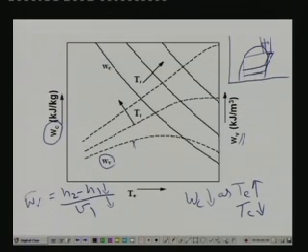So ultimately whether this reduces or not depends upon the relative reduction in this over this. You can see that initially as evaporator temperature is increasing, the volumic work of compression increases. It reaches some peak, then it starts reducing. The same thing is observed for different condenser temperatures, and you can see that this peak shifts to higher evaporator temperatures as the condenser temperature is increased. So this is the effect of evaporator and condenser temperatures on work of compression.